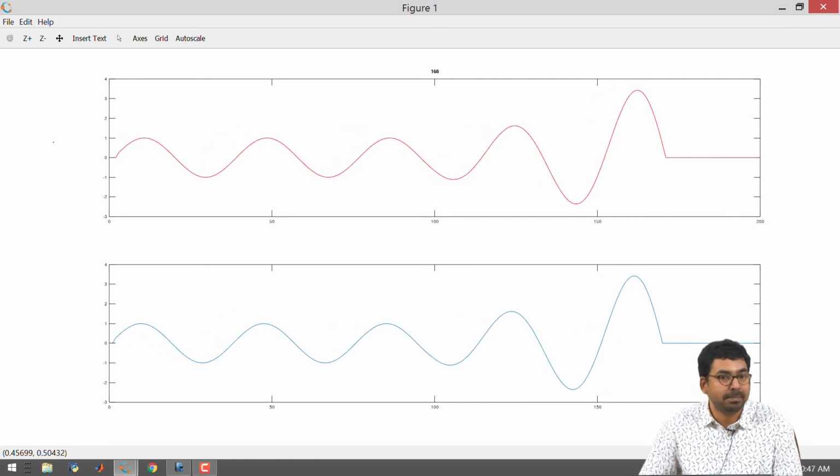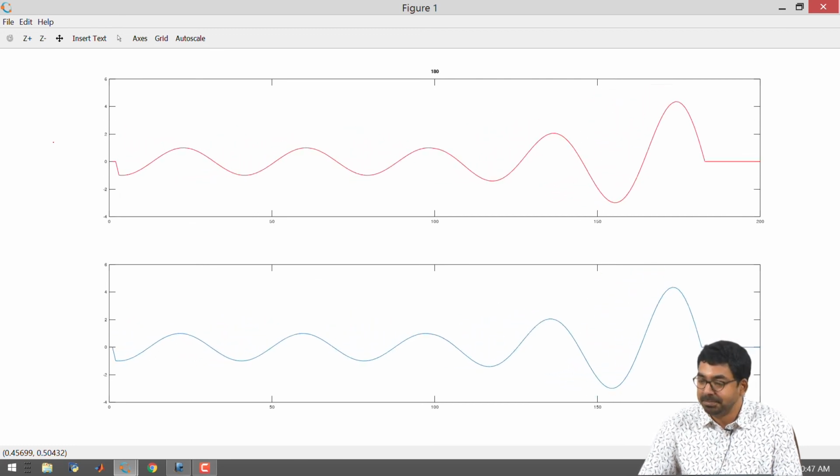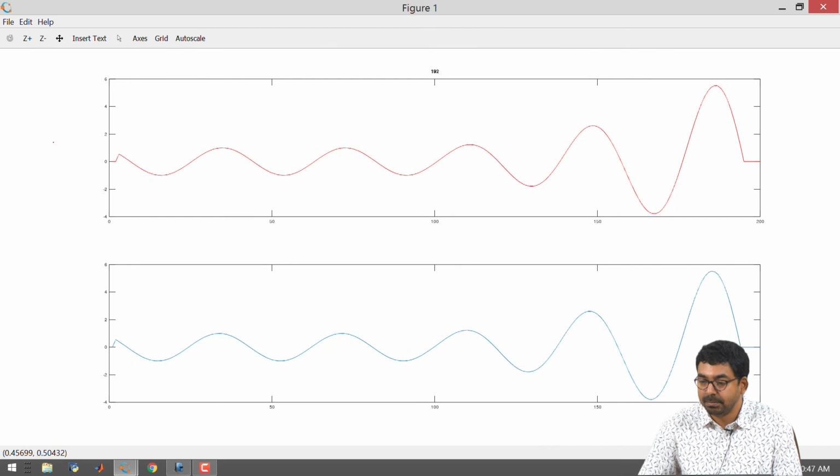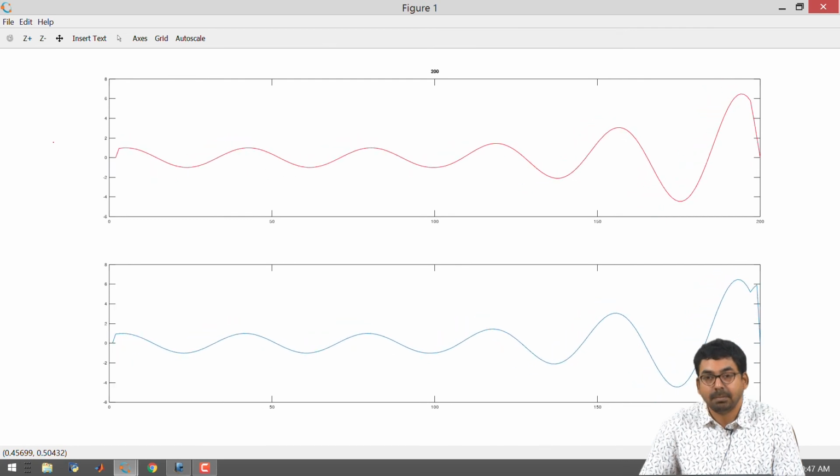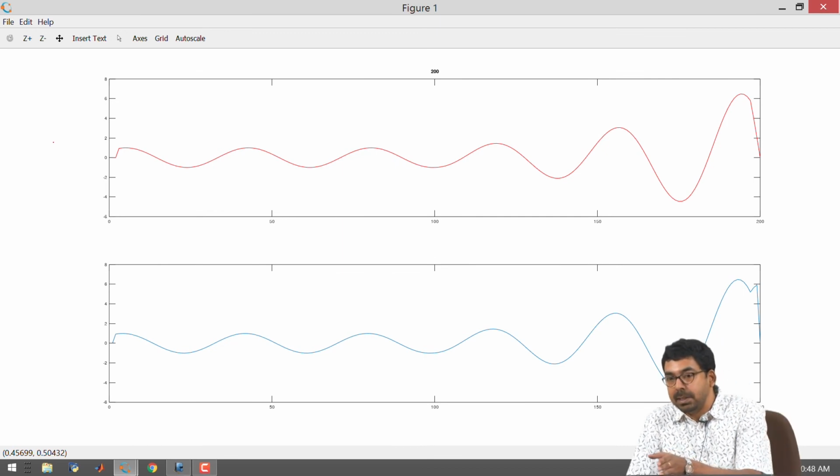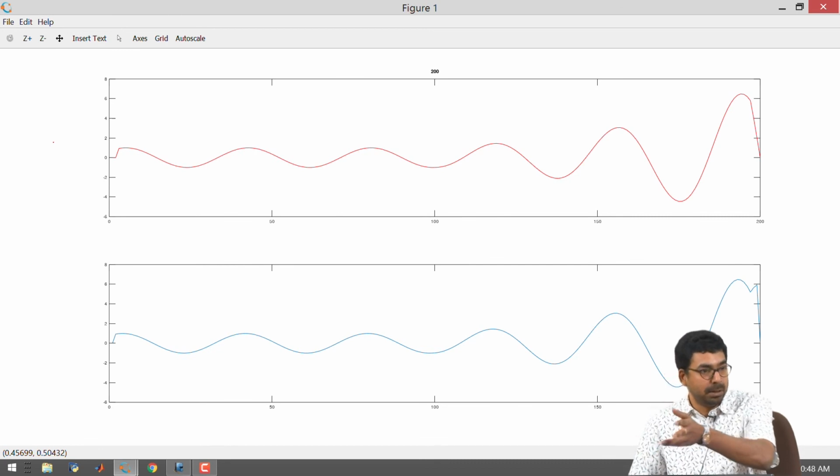Seems to be fine. Okay. So, R negative, G negative in our transmission line will give an alpha which is negative, alright, and that will mean that as it travels in the second medium, it is going to gain power, alright.